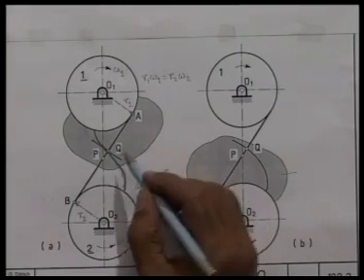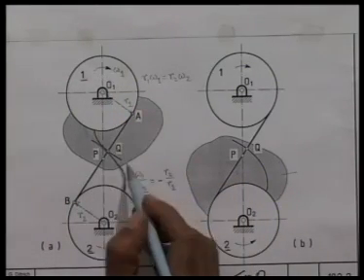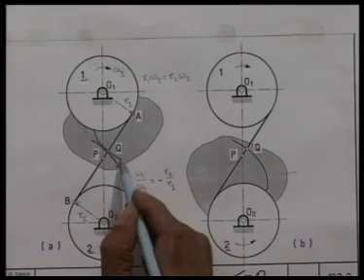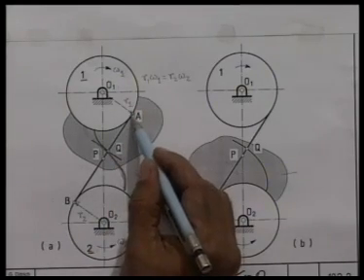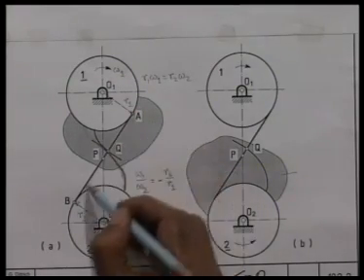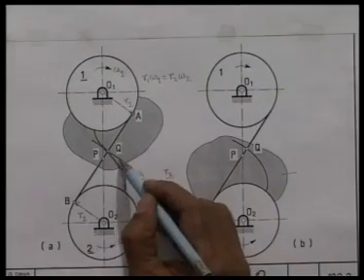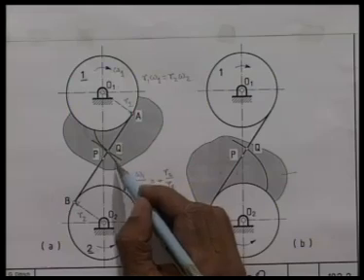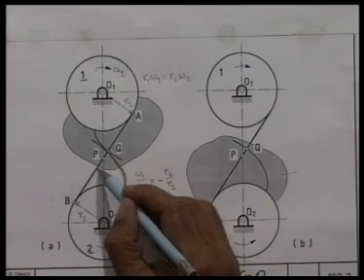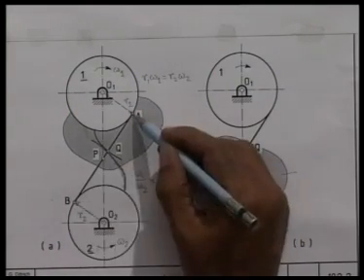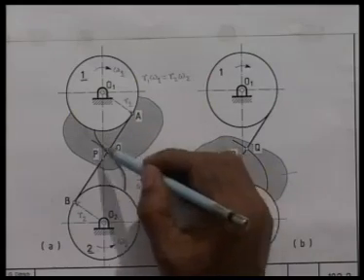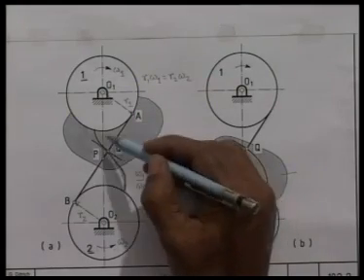The thing to note is that as this body rotates, the point of contact changes on both these profiles, but it will always lie on this line AB. A further clockwise rotation will make a counterclockwise rotation. This point may come in contact with this, but both of these points will lie on this line somewhere. So, this line AB is normal to these involutes, because this is the string, this is the involute.